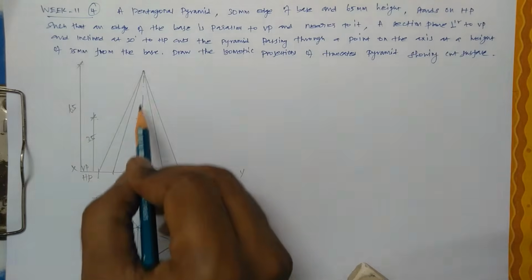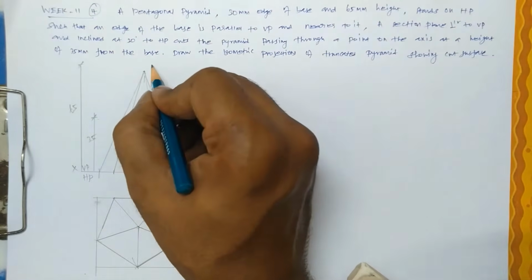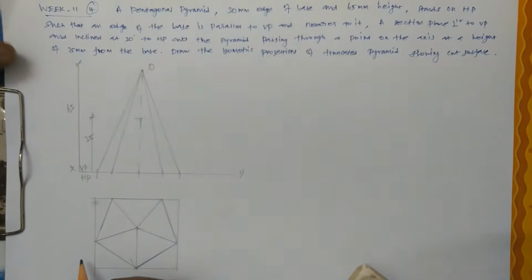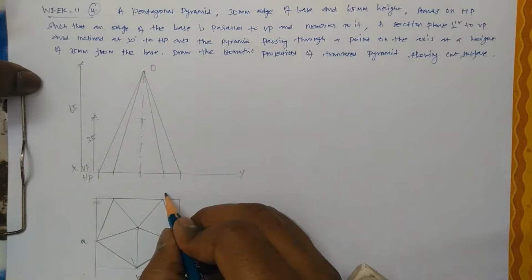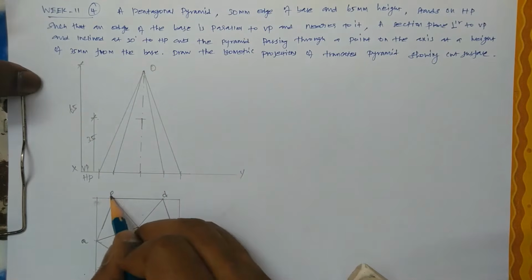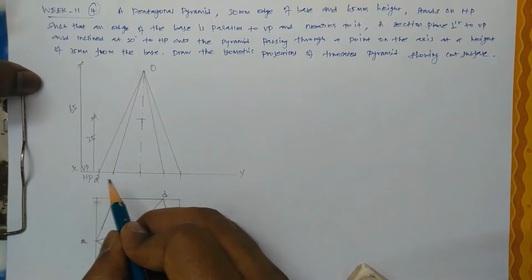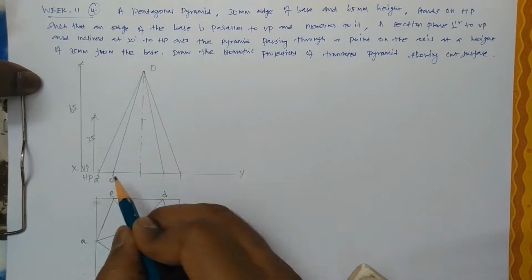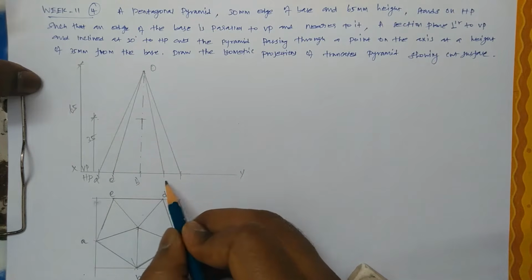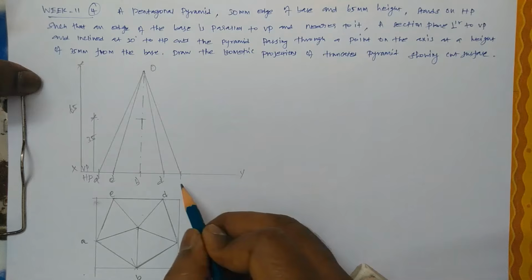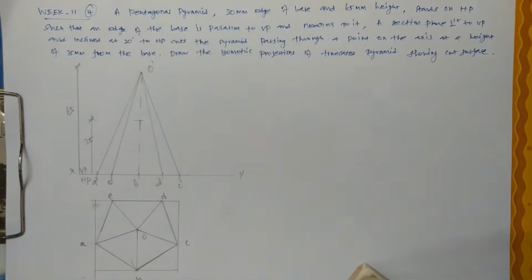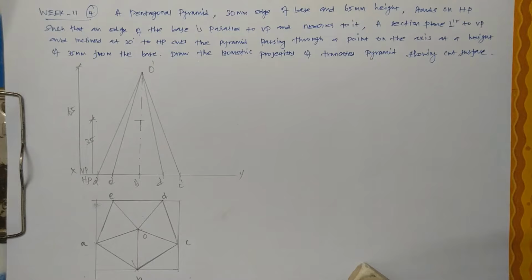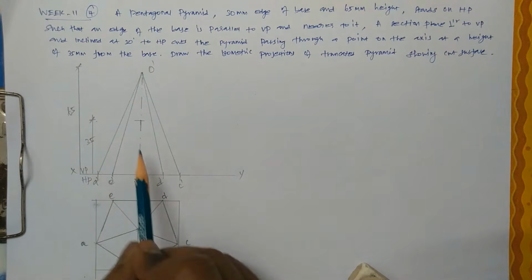So simple position, the height is 65 mm and 35 mm is just going to section it. From the base 35 mm we just going to section it. Now you just give the notation A, B, C and D, E, and similarly A dash, B dash, E dash, D dash, and here is C dash, here O dash, O. Yes. Now let us section this pentagonal pyramid